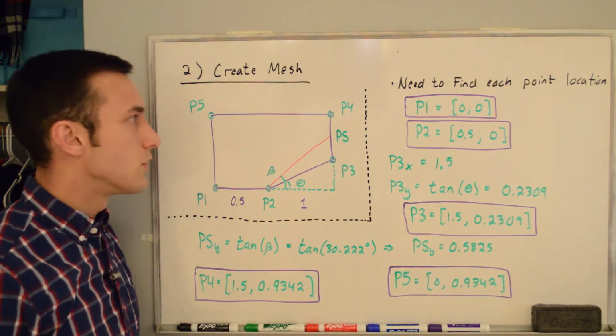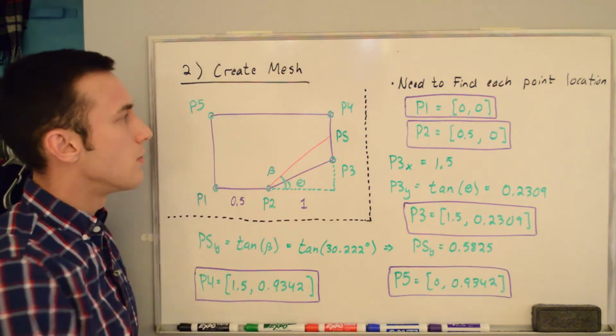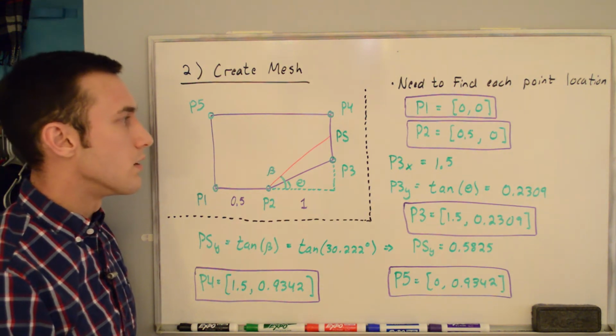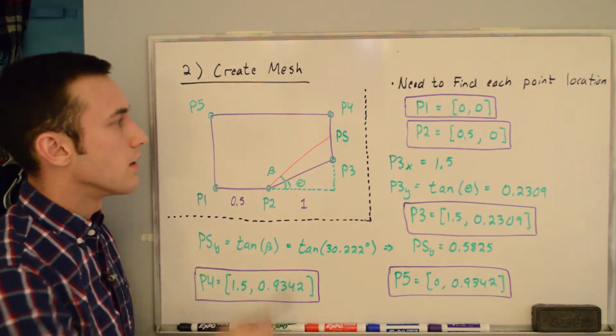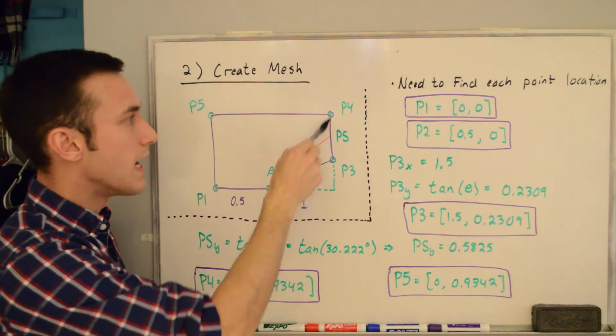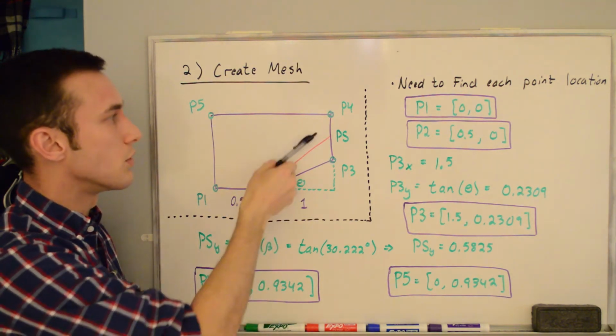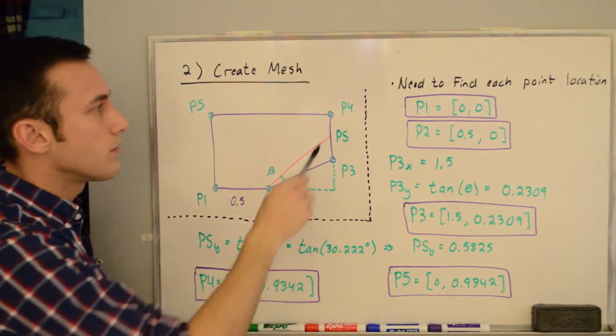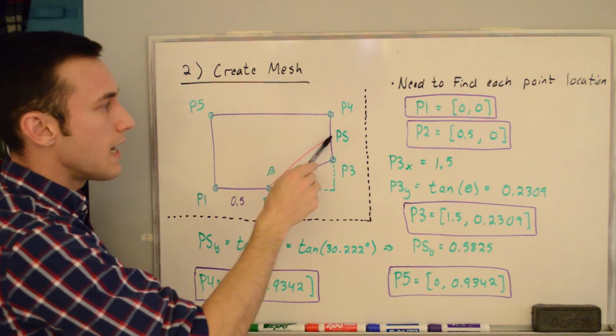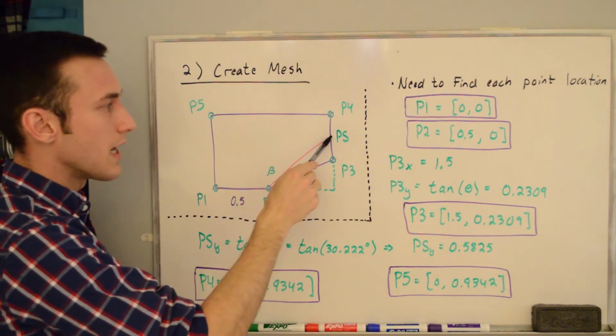The last thing we need to stipulate is how high the top domain, or the top boundary of the domain goes, and so the only stipulation here is that I wanted the oblique shock to exit the right-hand side of the domain as opposed to intersecting the top boundary. So we can find the PS, which is the location of the shock exiting the boundary.